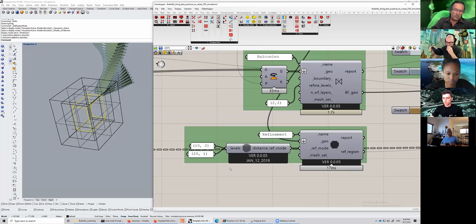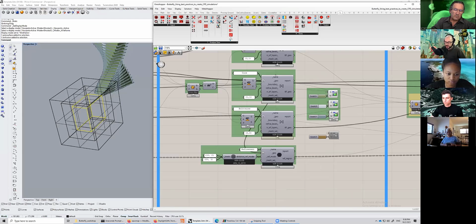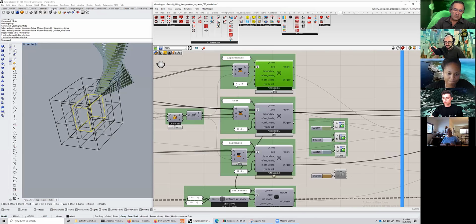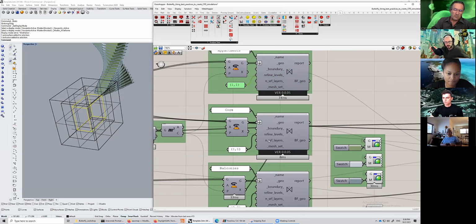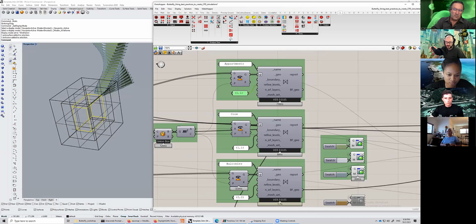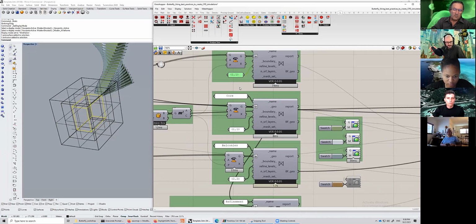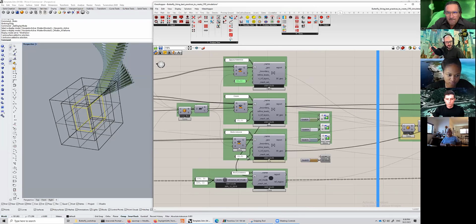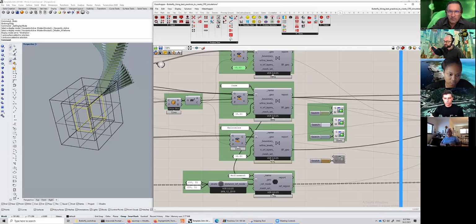Okay, so this is the first step. We create Butterfly geometries. Very simply, we just put the geometries here, and we can put refinement levels here according to how important these geometries are to us. You can also not refine here. I always refine once, if I'm honest. That's why I have it here. This is my best practice in a way. So this is what I want to show you today. I refine once, and then twice if the geometry is very, very important to me or very complex.